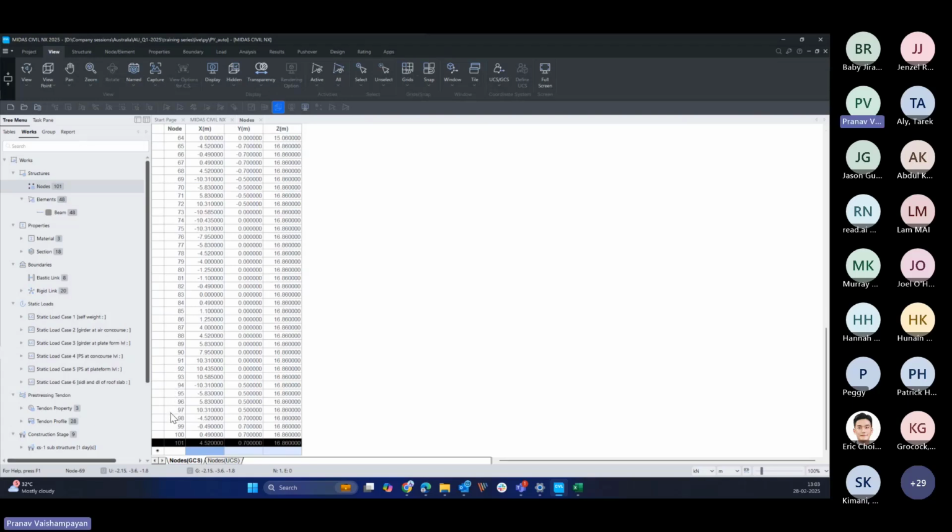If there are any missing node numbers, let's say I have skipped node number 79, then the plugin will not work. You should make sure that the total node numbers and the element numbers are the same, because in this plugin, we are generating the force deformation functions, and also creating the piles as we generate these force deformation functions. When piles are created, new node numbers are assigned.